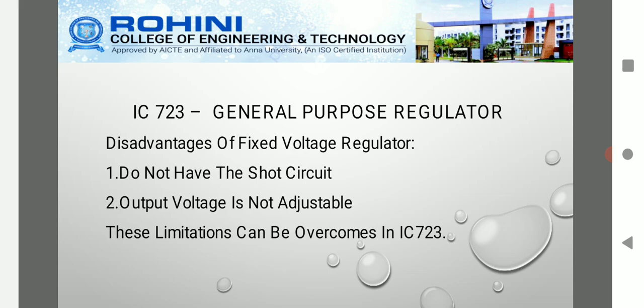While understanding the signals and the higher possible frequencies, we can find out the accurate measurements in the analog to digital converter. So these analog to digital converters are of four types. First one is successive approximation analog to digital converter, delta sigma, dual slope, and pipelined analog to digital converter.